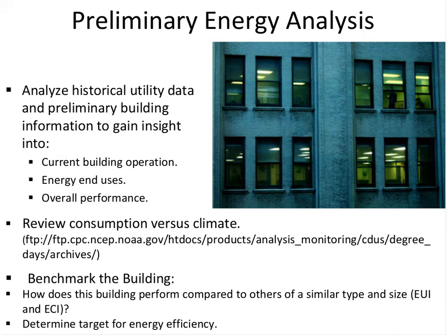And then you're going to review the consumption versus climate. By this, and I'll show you, you're going to plot each month the energy consumption, if it's electrical, versus cooling degree days, if it's thermal, say gas, versus heating degree days. And there's a URL there where you can get the data from the U.S. government. You just pick the location closest to you, which is the best you can do.